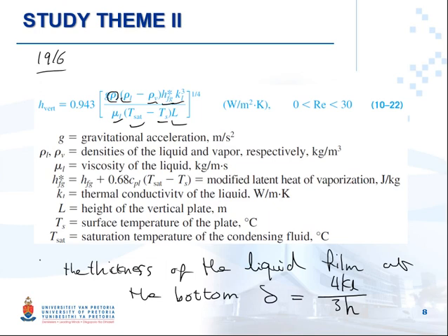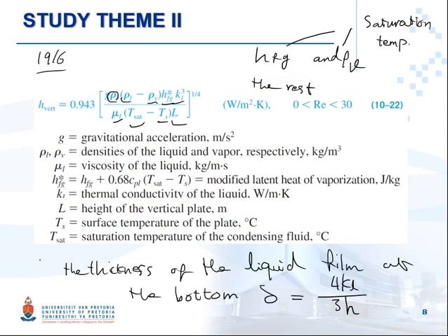As I mentioned, all the properties should be evaluated at film temperature except HFG and rho V. These two need to be at saturation temperature.